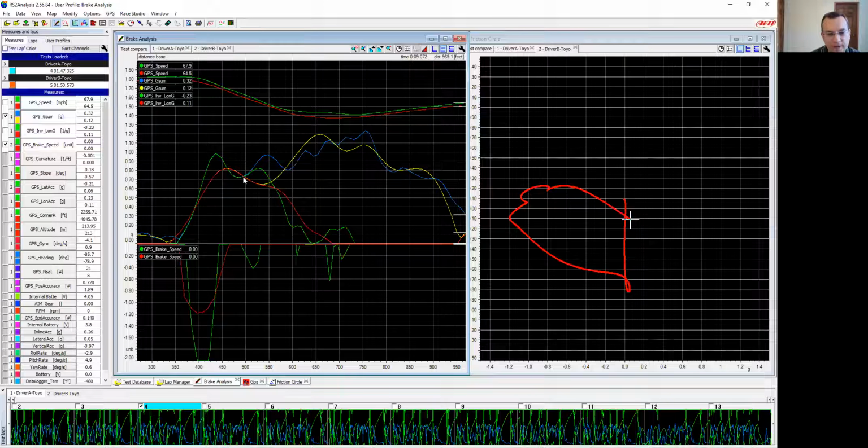If you start to be too aggressive on a corner, you'll find you get funny shapes in your friction circle plot, where you start getting those loops and things where you've exceeded the friction and now you're recovering the car in the middle of the turn. Yeah, chasing it. Maybe you're chasing the tail, or maybe you have a push or something.